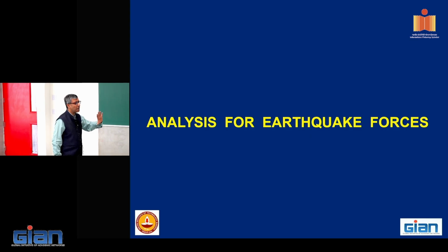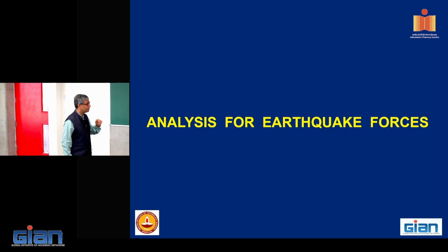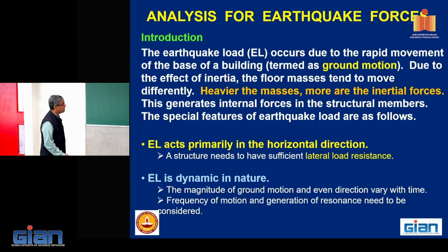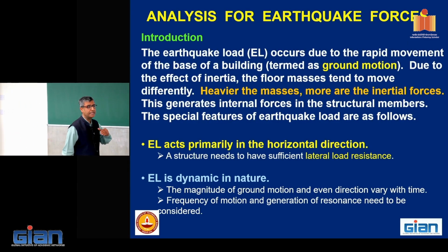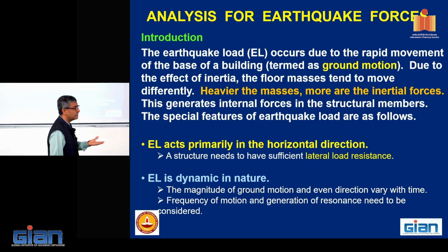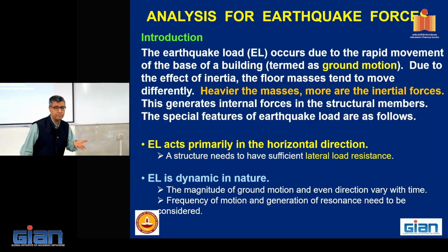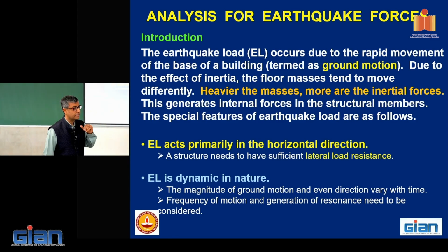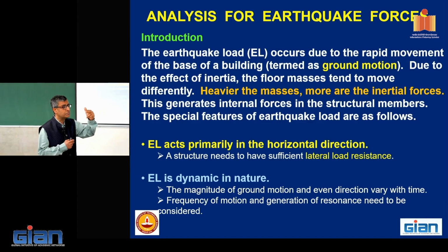Okay, the design part, the detailing specifications, I'm not going further. Next comes the earthquake forces. Now, earthquake force is not a true force. It is an inertial effect. What it means is there's a ground shaking, and since the masses of the buildings cannot move simultaneously, they fall back, and that's why there is a relative displacement between the different levels, which generates internal forces in the supporting members. Okay.